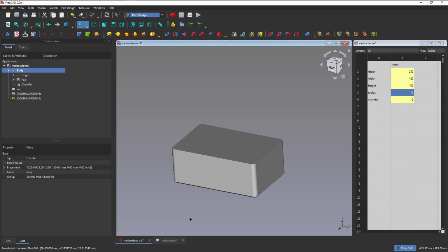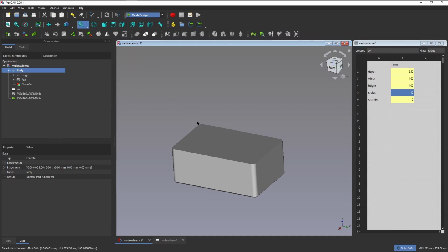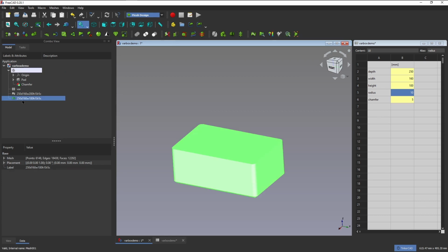Once you have your body and your body is finished, the way that you get it out of FreeCAD is to use the mesh design. Keep in mind an STL is a mesh. It's an external surface. It's not a solid object. So you go into mesh design and then you create your meshes and then export your meshes. And so working through the workbenches is how you complete the tasks in FreeCAD. Once you know those basics, you can generate and create your own files.